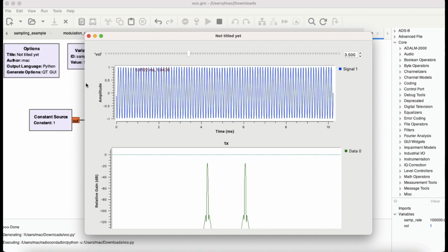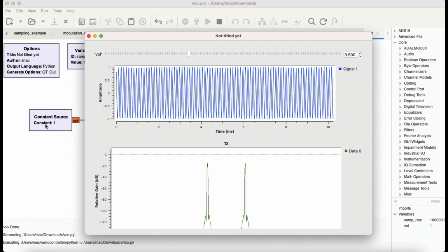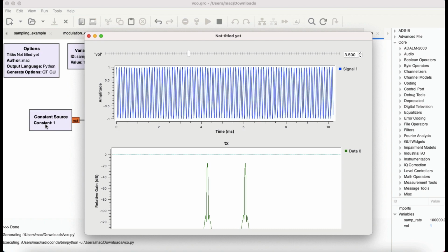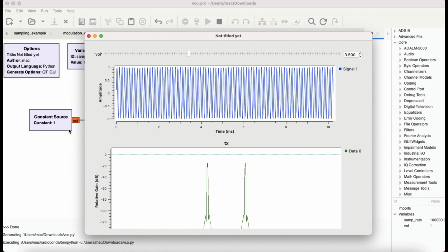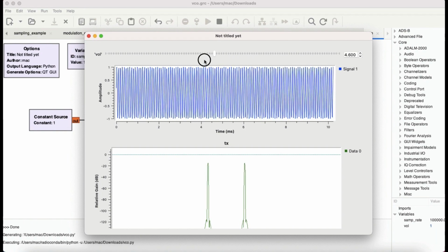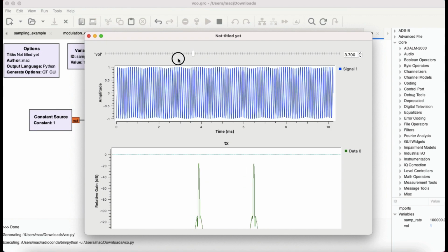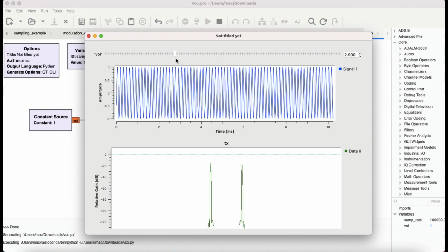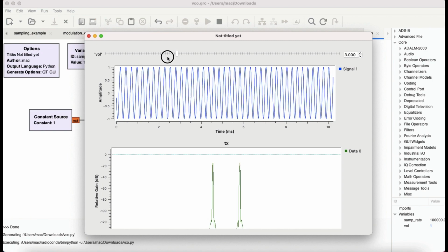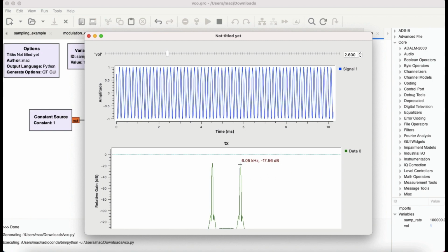But in FM modulation, we were controlling it using some type of modulating source. Here I just wanted to show you the functionality of the VCO. That's why you can use a slider to check and see. So now it's supposed to give me a frequency based on my voltage value. So you can check and see, yes, indeed it is.